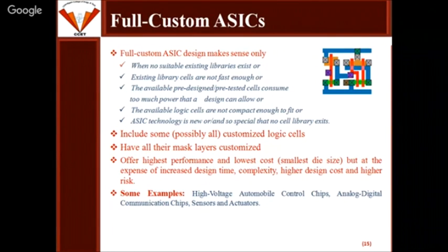No, the basic thing is that in the front end tool, we already take the help of the design library. In the library, some gates or some devices are already there, and we are basically utilizing them. We are not creating those gates. We take the gate, make the interconnections, make our device, and forward that netlist to the FPGAs and try to verify its working.